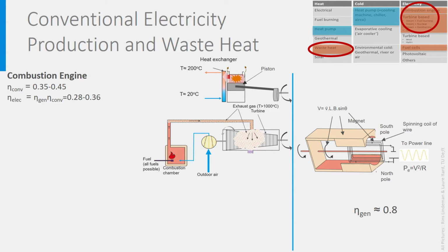The higher the pressure of the gas, the more energy it contains, so the combustion takes place at a high pressure and therefore also at a high temperature. You already know that air is needed for combustion, so the point here is first to compress air at a high pressure before injecting it to the combustion chamber. You see the compressor in yellow in the figure.